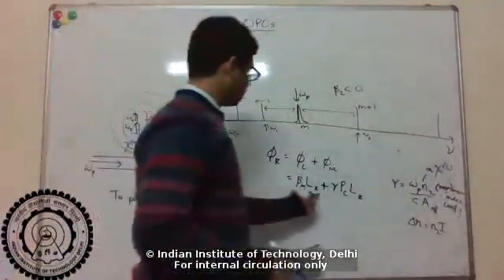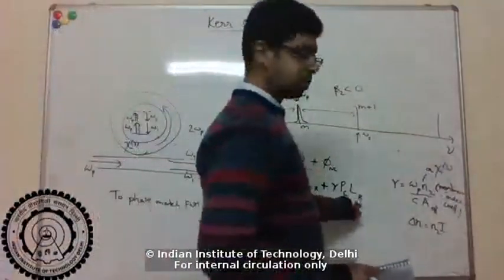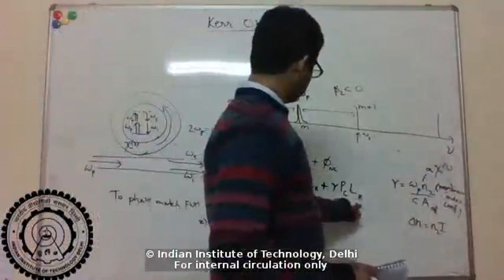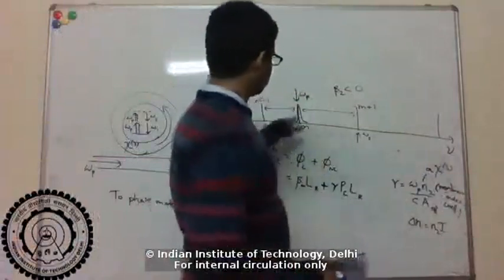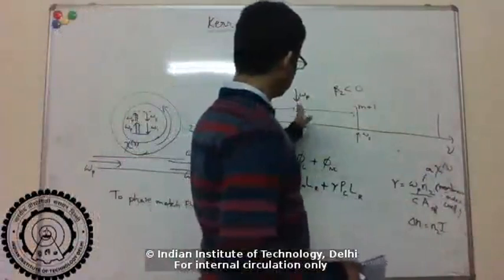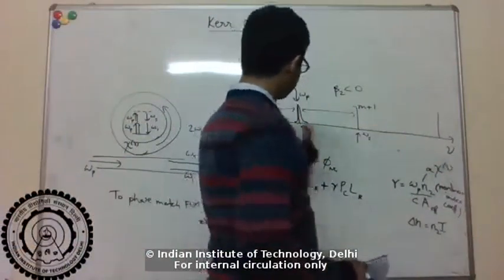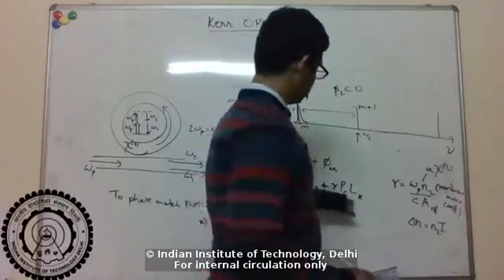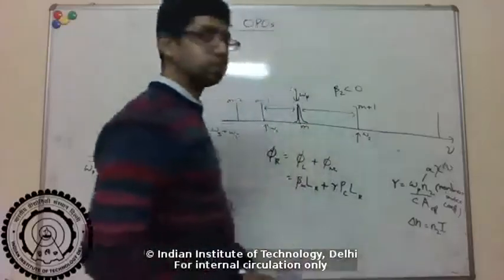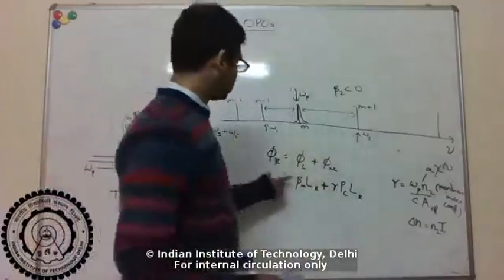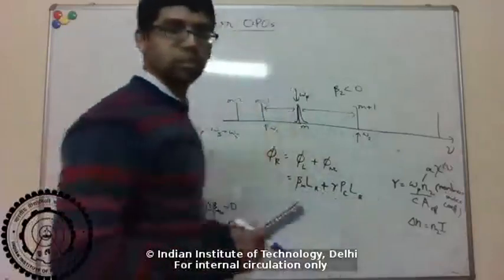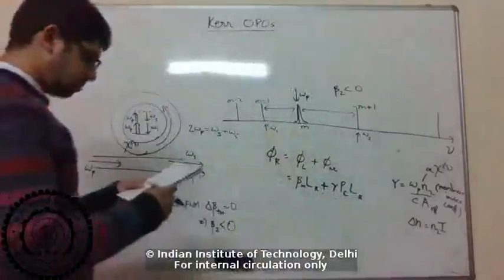So you can see there's an extra phase shift here, which means that the resonance frequency that we've calculated just from this will be slightly shifted because of this extra phase shift. So the condition is now that this whole thing is a multiple of 2 pi.